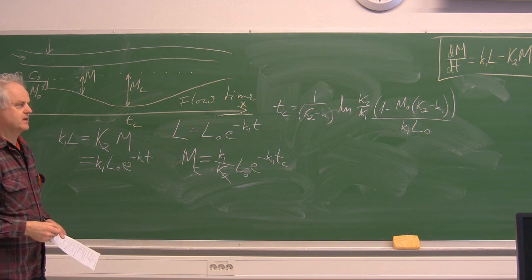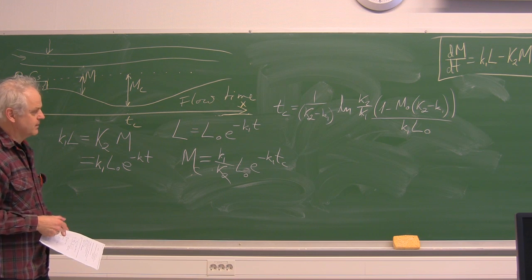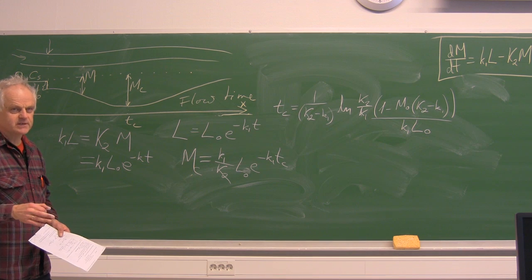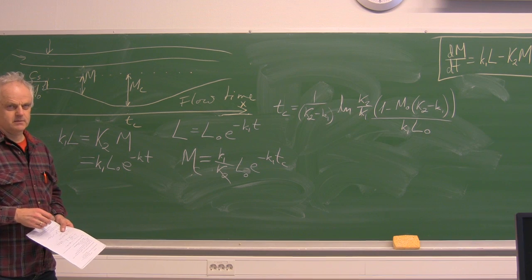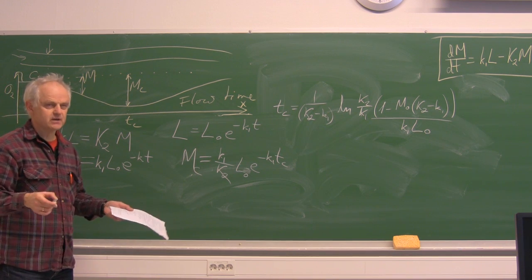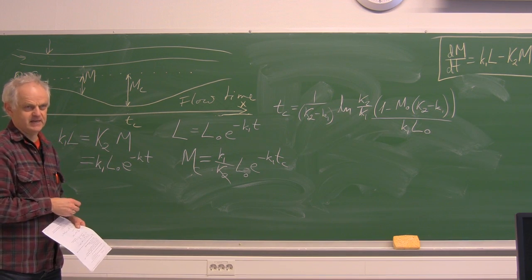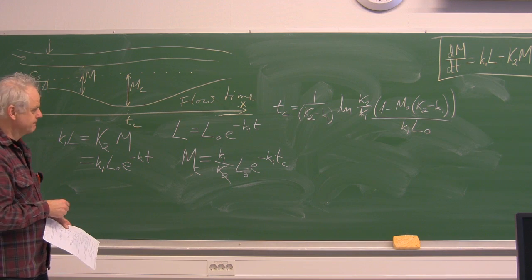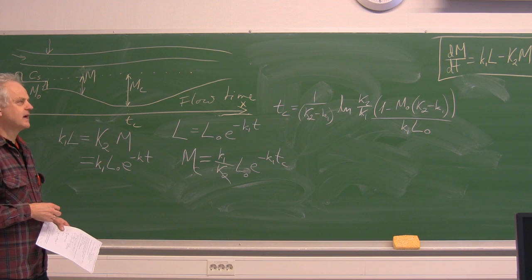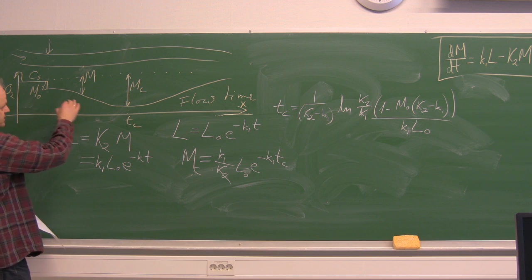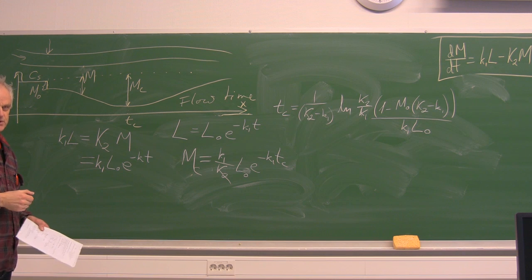That's how it's done. But of course, you could probably do it more easily just by making a model in the computer. And if you notice, Aquasim even has something called a river compartment. So instead of using the CSTR compartment that we always use, you could use the river compartment and do this type of simulation. But this is the basics of the Streeter-Phelps analysis of oxygen depletion or deficiency in the river caused by a sewage discharge.